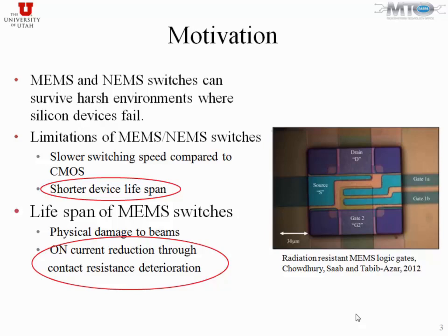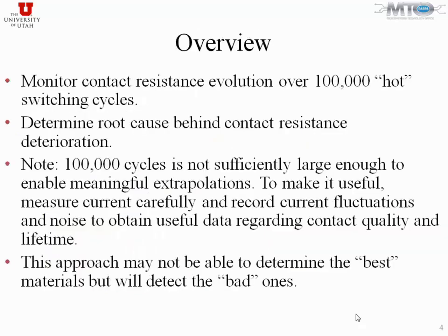So if you look at mechanical switches, they offer you multifunctionality. By that I mean, if you have a MOSFET, let's say, you can use it as an on and off switch. But if you have a mechanical structure, you can pattern different metal traces on it, and with one device you can have an AND gate, OR gate, XOR gate, stuff like that. So that way you can reduce the number of movable parts and improve their lifetime. And we have a 1-bit adder that is completely integrated on the same diaphragm, and when it goes up and down, it performs the computation for you.